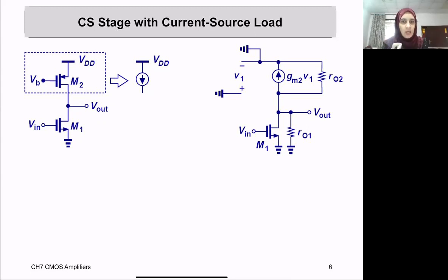Typically, if you want to create a large impedance, you need a larger area on your chip, and area costs money. So it is bad to use a large area just for creating an impedance. That's also a disadvantage that comes with using a real resistor. So in most circuits, they try to use transistors to replace the resistors. So it's a good thing. Okay, thank you.